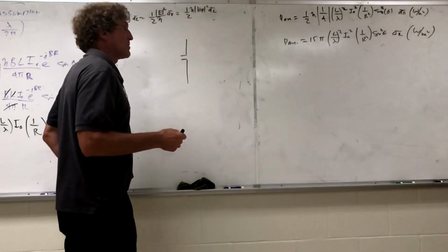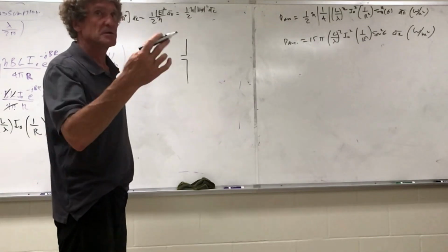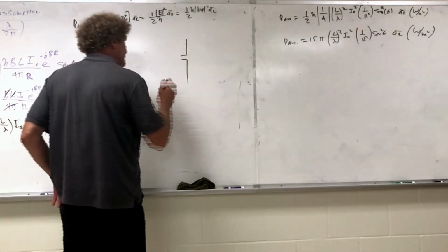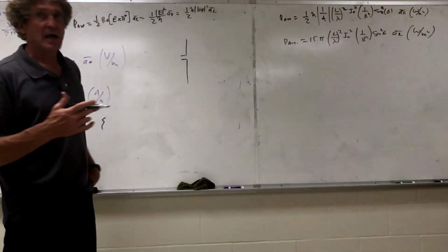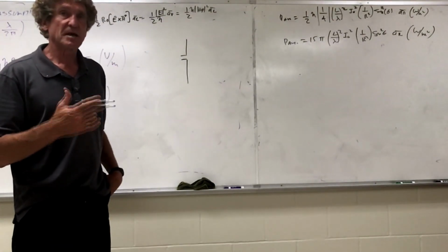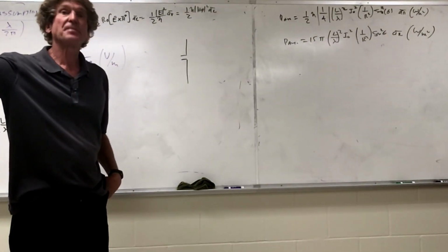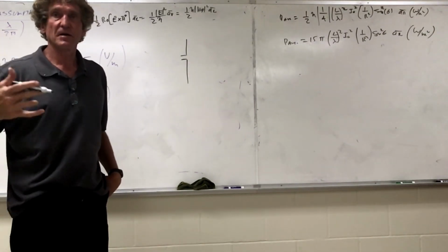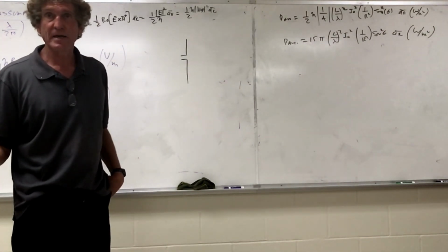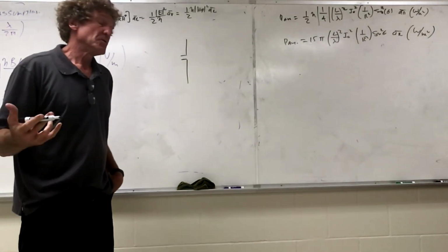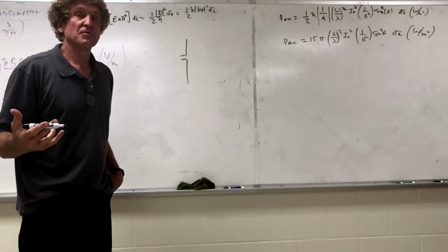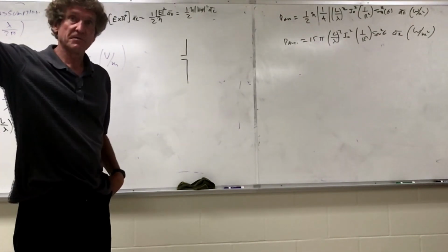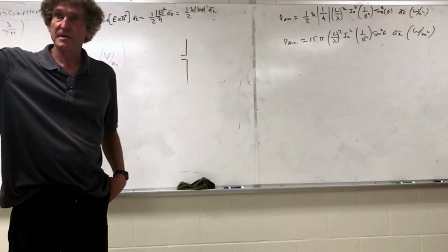Now we have to talk about one other thing for the short dipole. We're going to do this for all the different antennas. We talked about the radiation resistance, how this antenna actually has a resistance that's associated with the radiated power. It has nothing to do with an actual loss in terms of heating of the copper or anything like that. It's the radiated power. It's the transfer of electrical current power into photons of energy that are launched. You all with me, class?